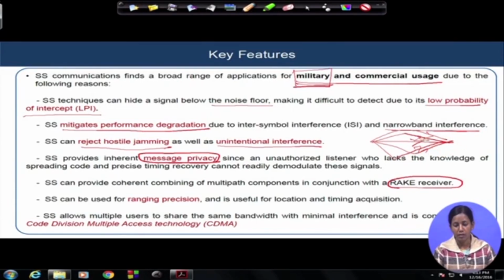The signals via the multiple paths are received with multiple delays associated with them. If you can capture those signals at their corresponding delay points and successfully combine them, we call the structure a rake receiver architecture.